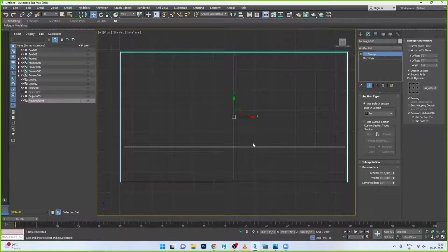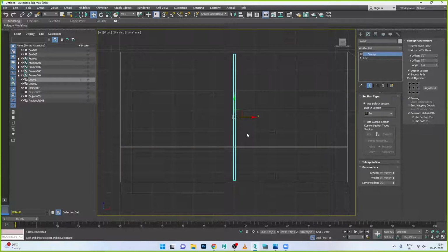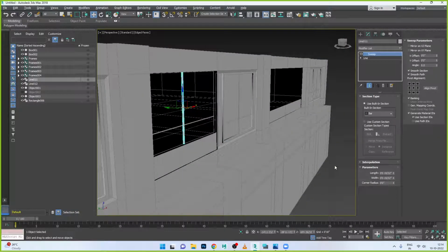Okay, almost done now. So now we can see it is a little less, so scale this one also to the right side, and take the move tool and organize it. Same thing for this pipe also, scale a little bit in height. Okay, done now. Move tool, Alt W and see the frame.